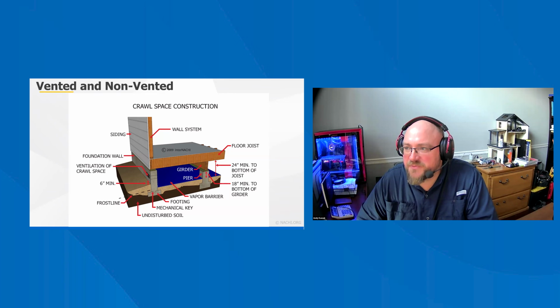When inspecting an unvented crawl space, the inspector should check the following factors: functional exterior grading and site drainage; air leakage between the exterior and the crawl space area, mainly at the top of the foundation wall and the floor's perimeter; insulation on the crawl space's perimeter walls and not the floor above, such as use of 2-inch rigid foam insulation on the interior side of the crawl space's perimeter wall; the use of 6 mil polyethylene ground cover in the crawl space with lapped joints; damp proofing of the foundation walls; the installation of an exterior drainage system if the crawl space's ground elevation is lower than the exterior finish grade; and some ventilation of the crawl space with conditioned air, typically from an HVAC system.